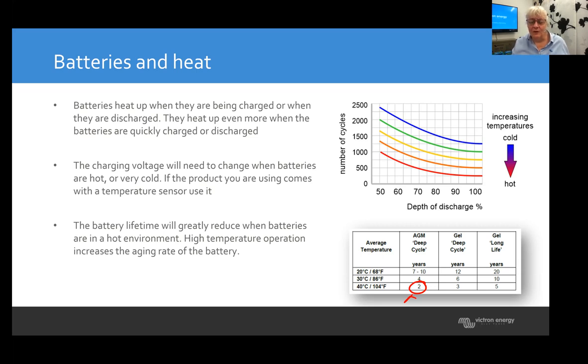So a lot of industrial type systems actually have air conditioning inside the enclosure where the batteries are, just to keep the batteries cold. Because sun they have plenty. It's heat they have as a byproduct. So it's important to keep the batteries cool. So duct some air conditioning in it. Put them in such a way that the heat can escape in the battery bank. You want to not bunch them all up really close together, and use temperature sensors.